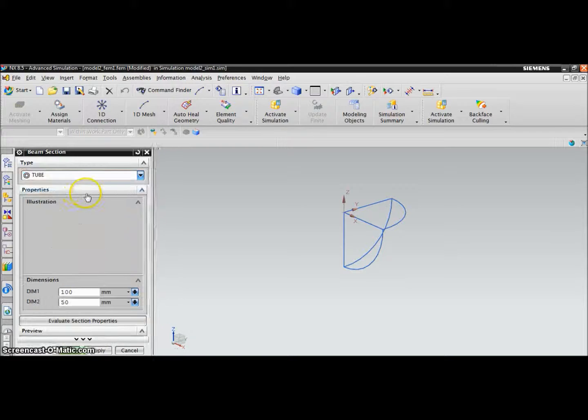Instead of rod, we use tubes, right? We use steel tubes. For this, I think I made it like this side length is 50. I can't remember what size tubes we use. I think like 25.4 millimeters in the outer diameter. I don't know, we'll say 20 millimeters for inner diameter. Whatever size tube you guys are using, make sure to input the inner and outer diameters correctly with the correct units.